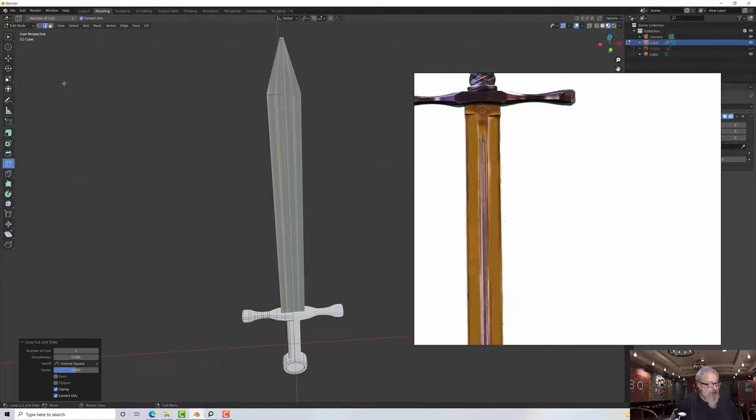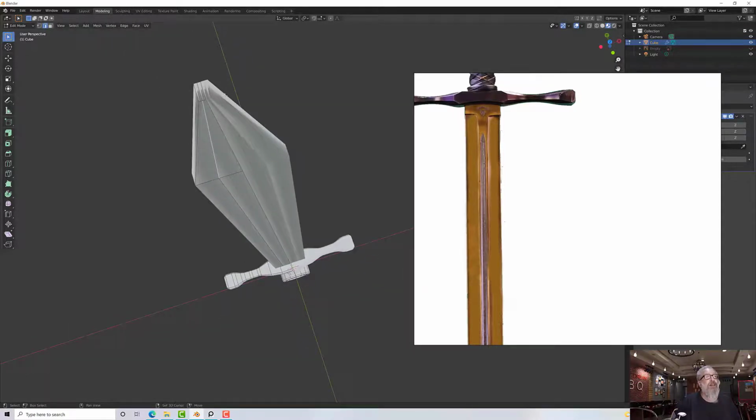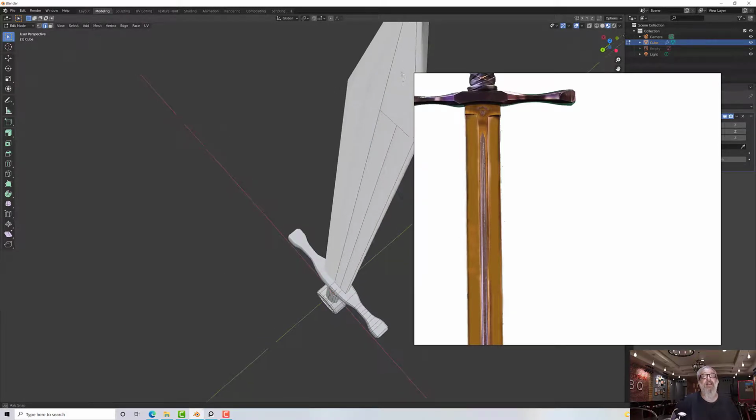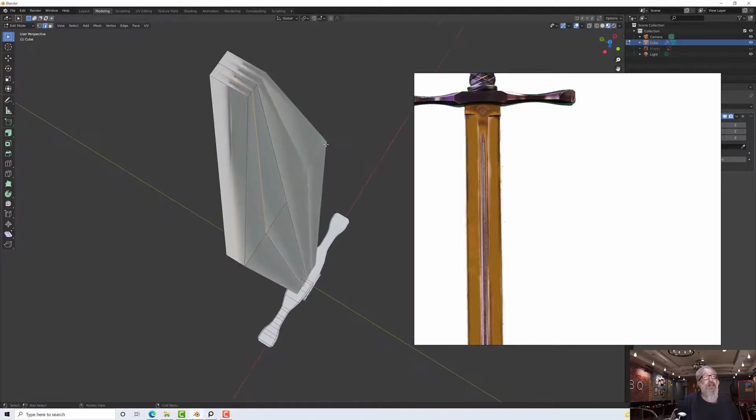So let's go to select, press W. I'm going to select these top edges here. This one going across and the one going down the other side. You see it's all starting to pinch and go a bit weird up the top, and I don't want that, so let's dissolve these edges. So it's right click, delete, not right click, it's just delete, and dissolve edges.